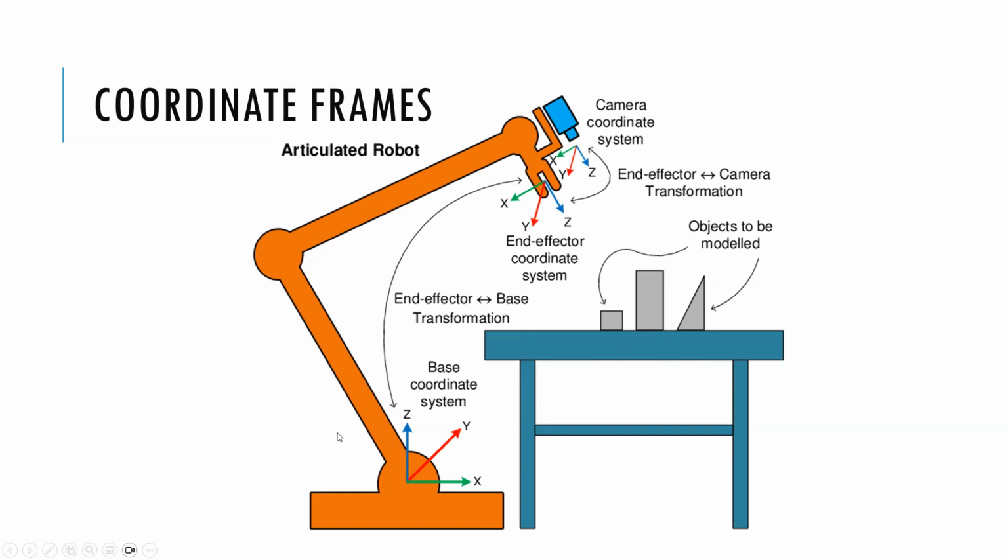Today, we want to program or tell the robot to move the end effector position to go to an object. Say if I want to grasp this object here, we discover where this object is located using the camera, but now we need to be able to move the robot to go there. So we need to set the end effector pose equal to the object pose, and then we need to compute the joint variables.